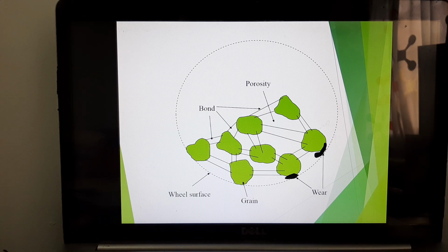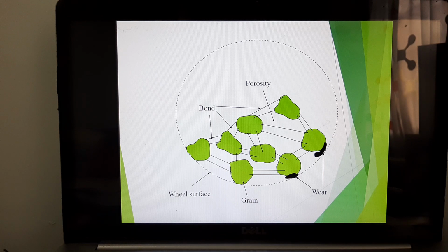Rough grinding will not significantly change the dimension of the product, but it will remove material that involves a minute amount of change in dimension, because you are removing material to smoothen the surface. Therefore, there will be a very slight change in dimension, maybe 0.1 millimeters, 0.2 millimeters, in order for you to obtain a smooth surface finish.